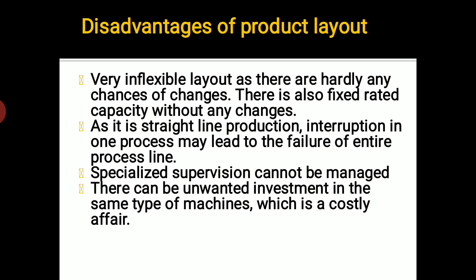Now if it has a set of advantages, it does have a set of disadvantages also. Disadvantages do not mean that we will not follow this, but it has its own set of limitations, and that should be kept in mind by the manufacturer, so that when he is deciding on his layout, he can take the decision accordingly. Let us check the first disadvantage. Very inflexible layout, as there are hardly any chances of changes. There is also fixed rated capacity without any changes. That means it is a very inflexible layout.